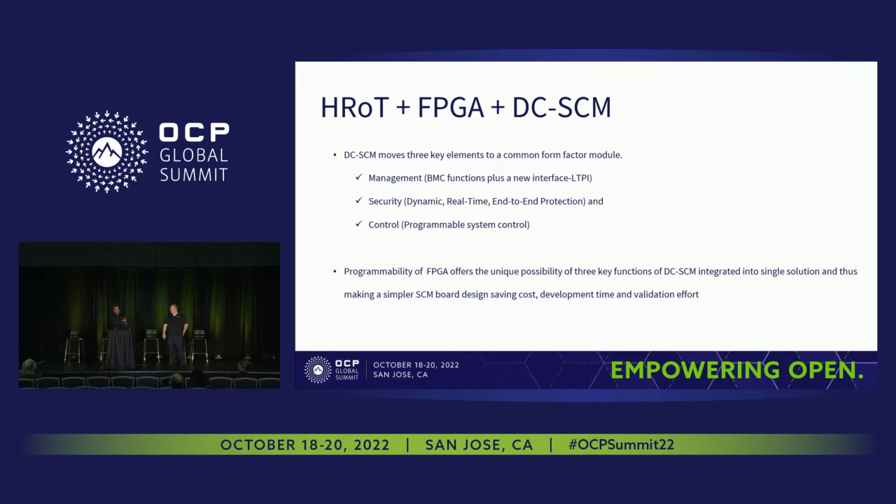So I think the big thing here is, with the security, you can do pre-boot conditions. You can validate all those things. And since the control mechanism is done by a single FPGA, you can do that. Once it is powered up, you can do constant monitoring of all the flashes, all the BIOS or BMC, or any privileged firmware that you want to monitor. You can also introduce attestation if you want to do that.